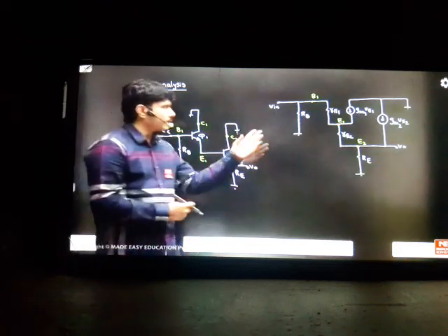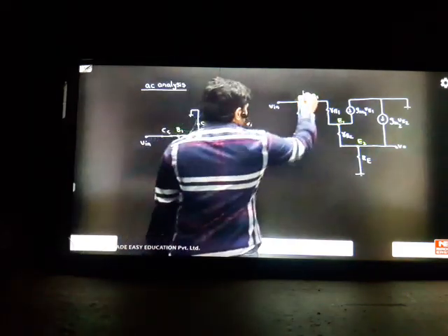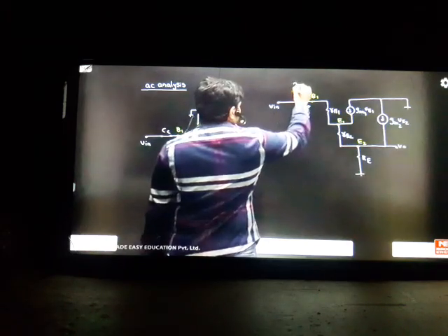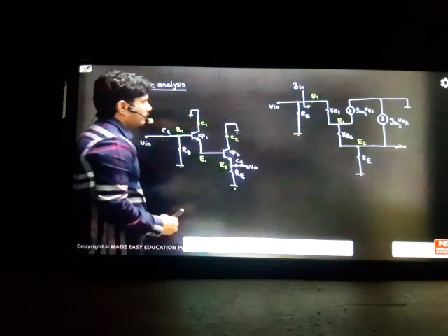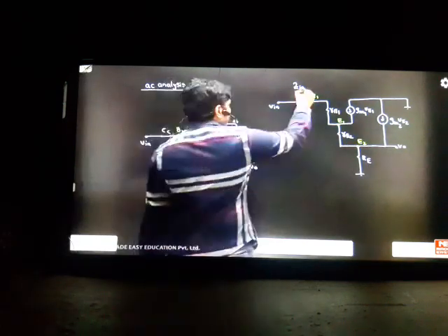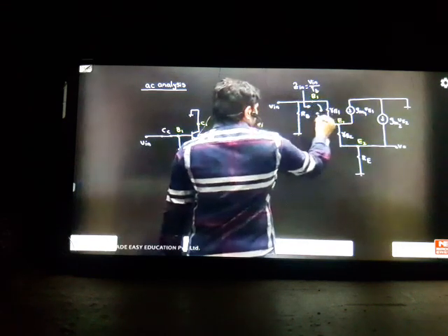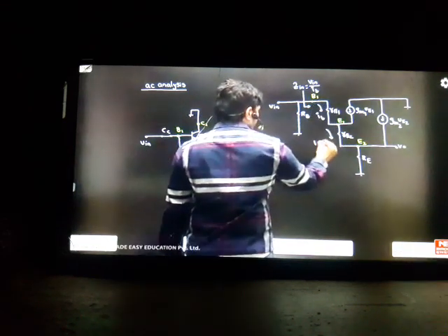It's very easy and comfortable. Just I want to know the calculations. Seeing the board, how do I calculate here? Suppose if I want to know the answer from here, can you tell me what is your ZIN from here? As a Darlington pair, if you want to know, you calculate from the base, not from the RB. Because Darlington pair impedance means transistor impedance you want. So ZIN from there I want. The formula you can write as simply VIN divided by IB current. This is the IB current. If this IB is going here, it will be going as 1 plus beta times IB.